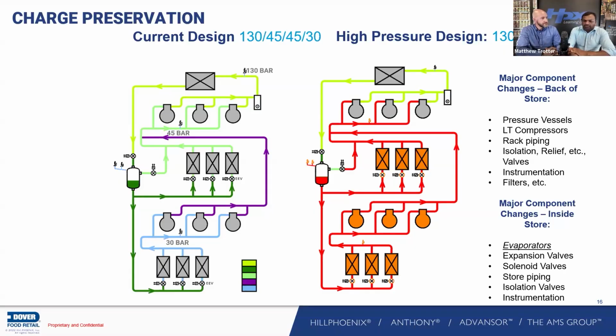There are certain companies that do 90 bar. We do 90 bar as well. Yeah, we have some industrial companies that do 90 bar. And from talking with those that come in for some of our classes, they say they're looking at a 25, 30% increase from system to system when they go to that full length with materials. And then there's a time function too. It's heavier, it takes longer. Yes, everything, the struts, everything has to be rigged to accommodate that, plus the refrigerant itself. So those are all the considerations, right?